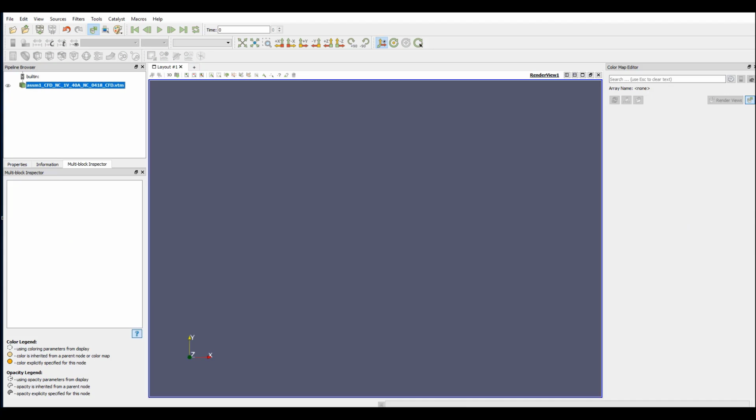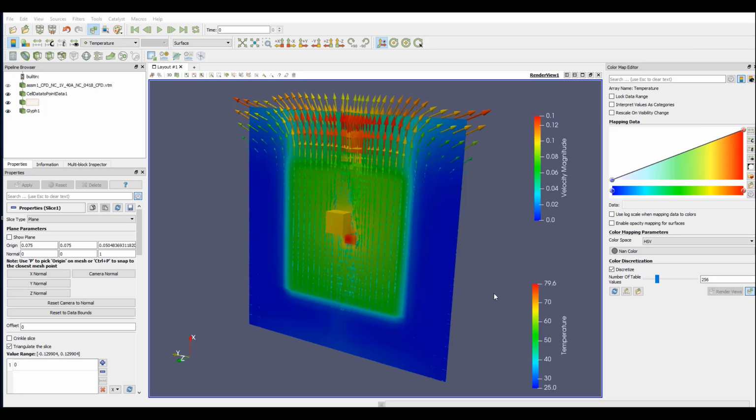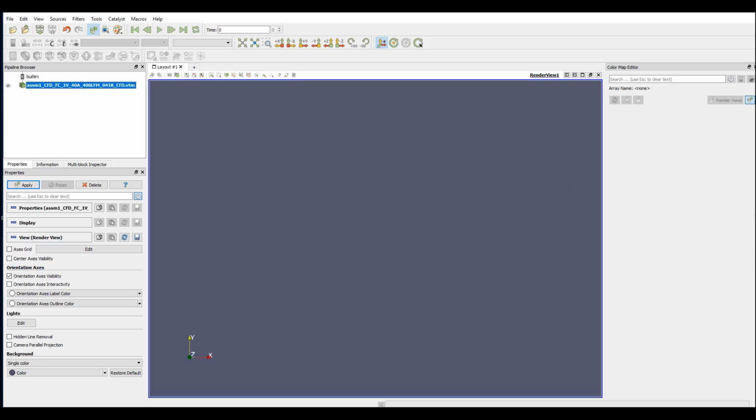Of course, we could do CFD simulation like before. Here we show natural convection results, the cold air coming from the bottom to the top, and all those components packaged on the PCB board are put into this orientation, like vertical, with the normal coming out of the screen. So you can see the cold air coming from the bottom and going to the top at this cross section. Also, we could do a forced convection CFD simulation, like placing this assembly in a wind tunnel.